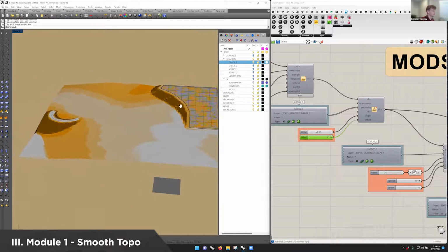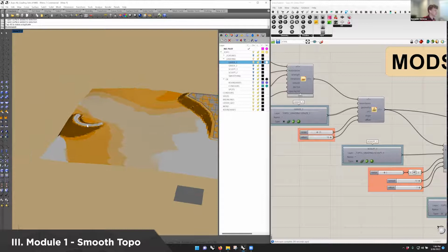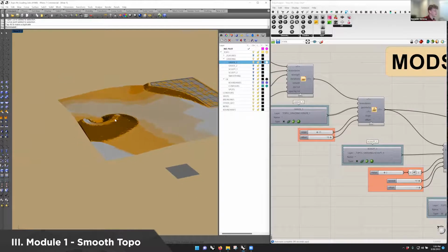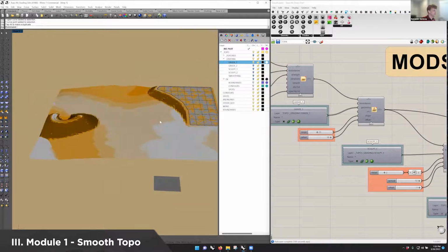But you'll also notice over here that I have a curve input as well. So right now I have both a surface and a curve being used simultaneously with this component. It will take any piece of geometry that you input. I could put in another point somewhere and it will automatically use it inside of this component. And then I can adjust that curve as well and it will update everything to adjust my curve. And so it's a great way to make big broad strokes as you're moving through the grading.